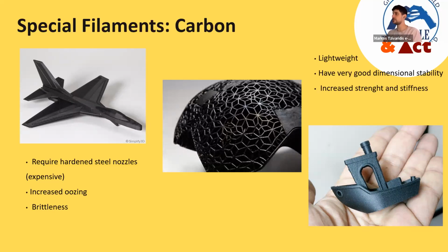Maybe you should better understand how 3D printing works and then move to this type of material, because it has very small parts of carbon fiber in it, which will be hard to print and may create some very bad occasions like oozing, which is not best for someone who starts 3D printing. You may be disappointed by the results.